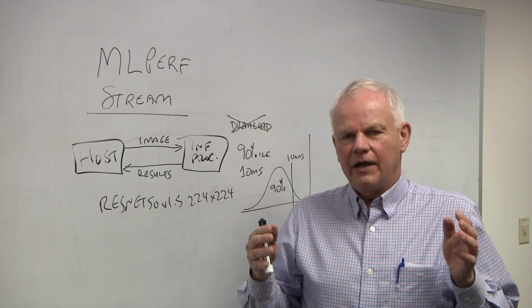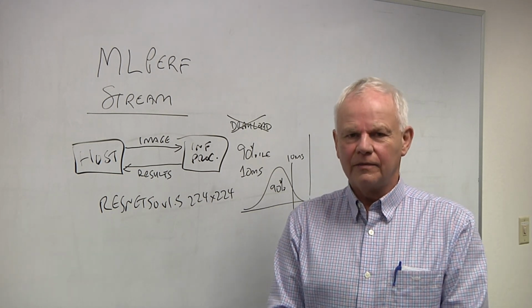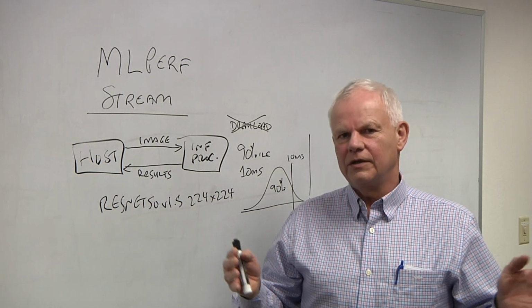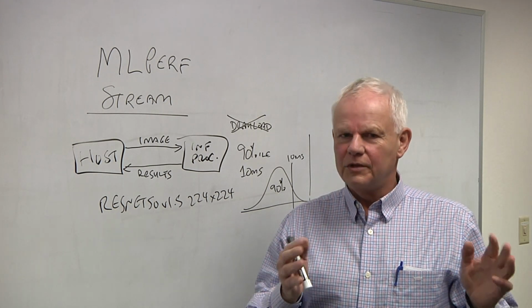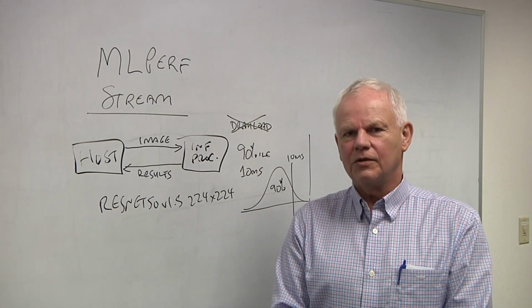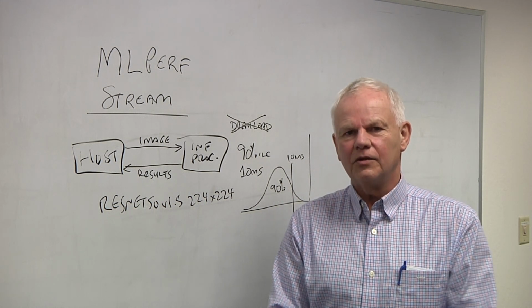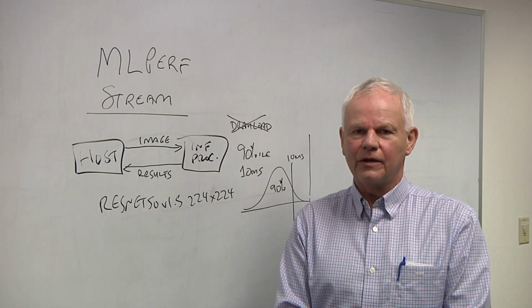So it means that you have to be that much more careful about the thermal environment that you put it in. And the reason there's limitations is if it ran at 100 degrees, it would be burning more power, it would run slower, there'd be something that would be an issue at that point. So again, there's some fine print that you have to check, not just the throughput. And not just the power numbers, you need to know the exact operating conditions for those power numbers.